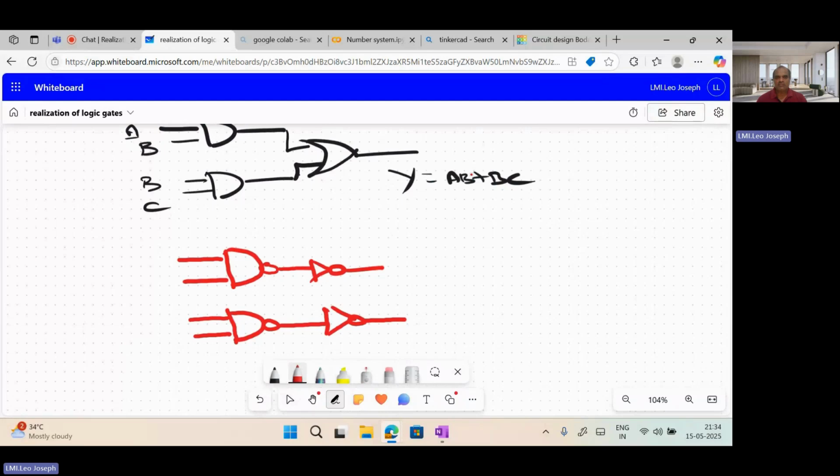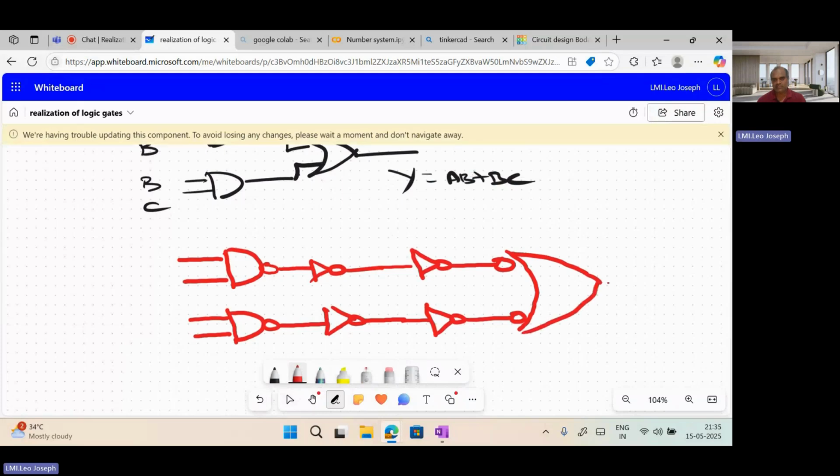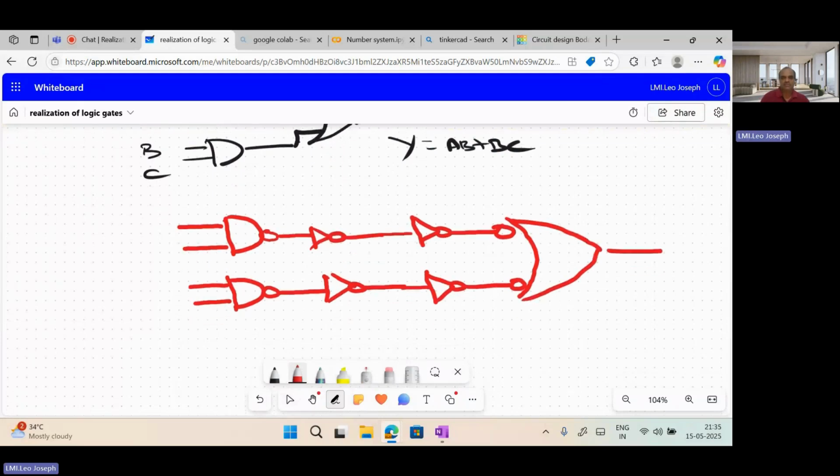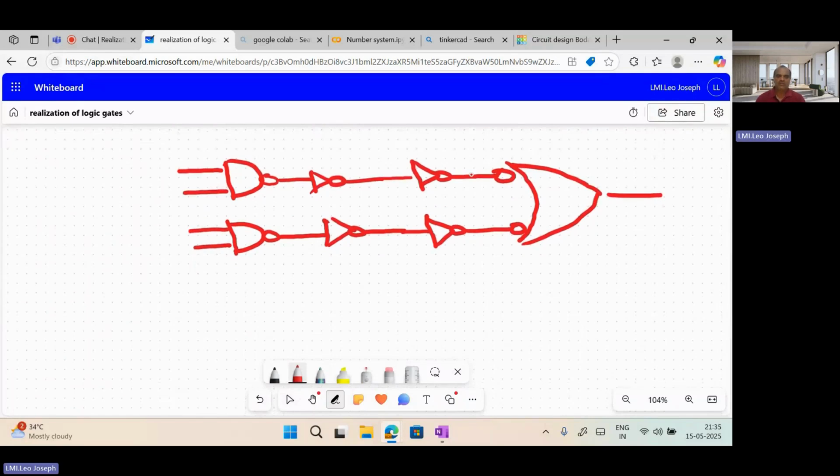Right. And then I am looking at one OR gate. Listen here. This bubble compensation, this bubble compensation. Now I am working on the OR gate. OR gate means what you will do? At the input, one more NOT gate will come. For compensation, I will add one bubble. Similarly, one inverter will have one compensation bubble. So I am just putting this OR gate as it is, right?